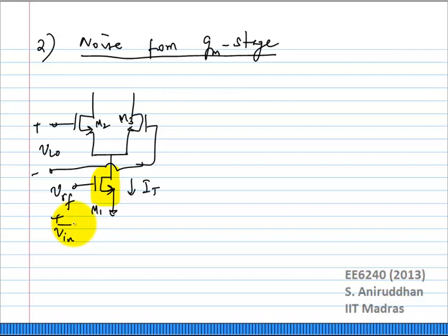I modulate it with the switching pair M2, M3, and I get a mixing action. What kind of mixing action do I get? I multiply your GM times VRF, which is IRF, right? So your IT plus IRF gets modulated by the switching pair. There is an S of T signum function. So the current gets switched on either side. We have calculated earlier what the overall transfer function is.